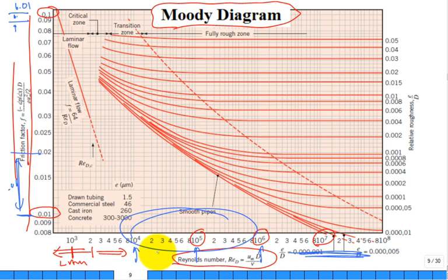Look at the friction factor. Somebody comes in and says, I just calculated my friction factor and it's 0.0001. Guess what? It's not on the diagram. It's too small. Somebody else comes in, oh, my friction factor is 2.13. Really? We need to check our math, because where are we at? We're over, it's too high. So anyway, between 0.01 and 0.1 is the vast, vast, vast majority of applications.